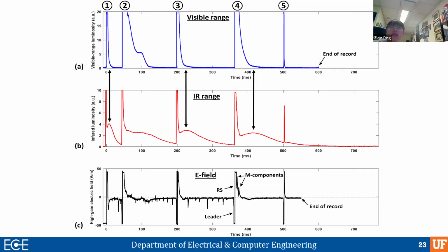For the ultraviolet, it's a bit higher because we need to image streamers, which are more transient. For that, we have one UV imaging system operating at 49,000 frames per second, and another at 15,000 frames per second. So the interval time, which is the time resolution, is different from the exposure time.